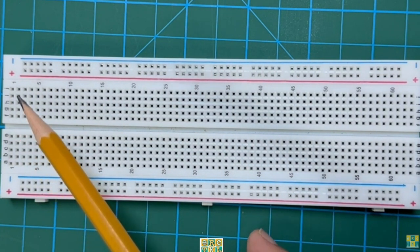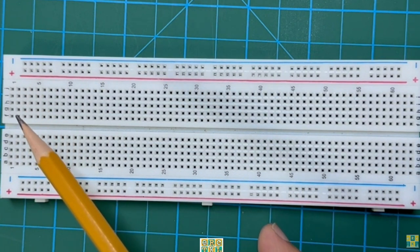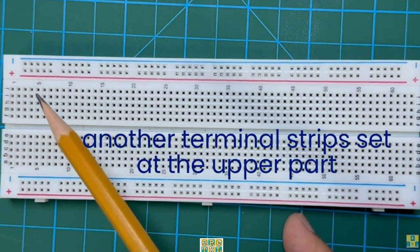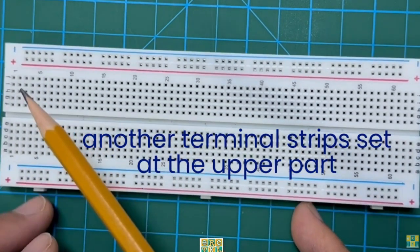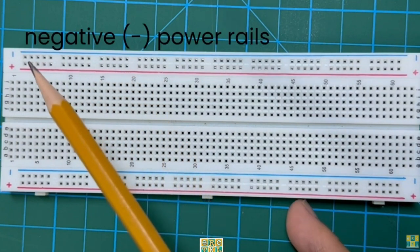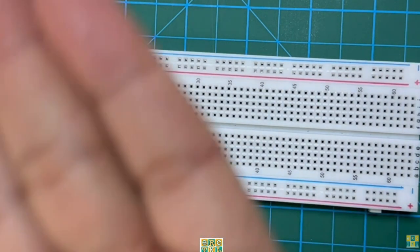On the top part, you will also see F, G, H, I, J, which you can also use to connect your circuit. These are another terminal strips set at the upper part of your breadboard, up to 63 also. And we also have positive power rails at the top, and also the negative power rails at the top. So this is what we call as breadboard.